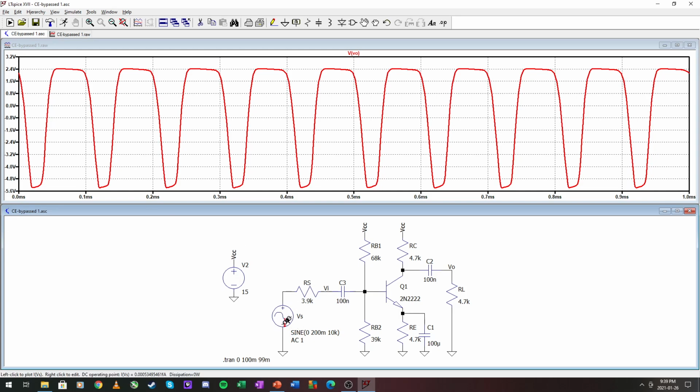the linear amplification from source to load, and then what is our amplifier's capability when we don't consider linearity, but we do care about the output signal actually clipping. Okay, so the input range of our common emitter amplifier with a bypassed emitter resistor is actually really small.